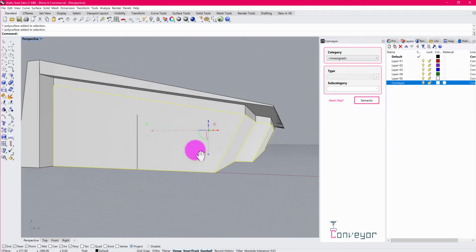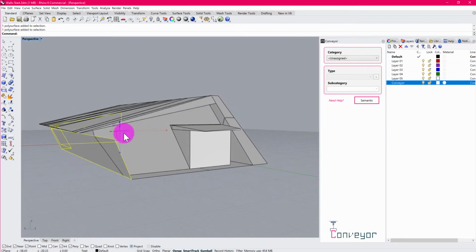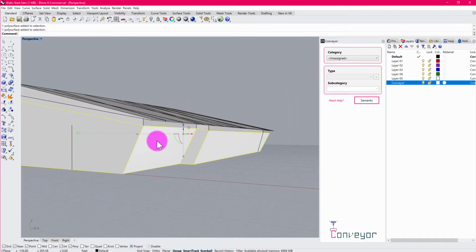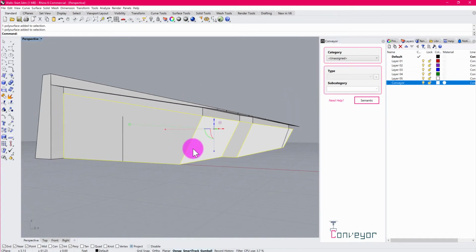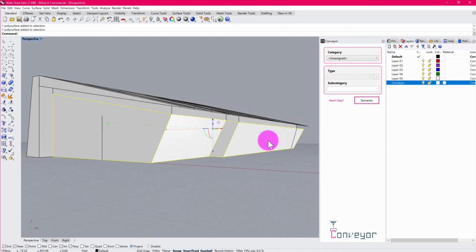and there are some surface segments. You can see these are joined together along these seams, working the way around the building. And what we can do is actually use this surface as a driver for a face-based wall. So if you're in Revit, there's a workflow where you might create a mass, a conceptual mass of sorts, and then you're able to apply face-based wall types to the surfaces of the mass. What we can do here is use this surface as a driver for that same operation.